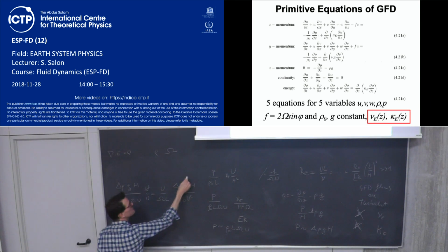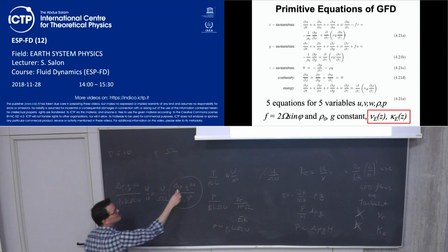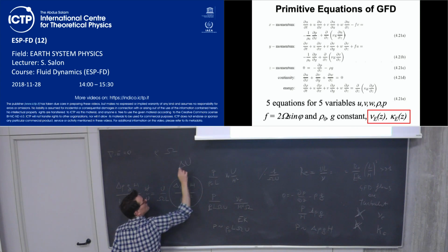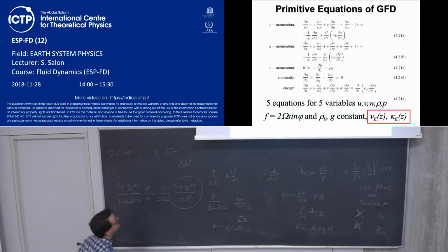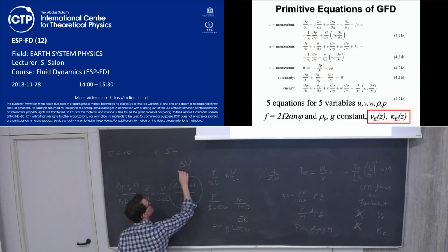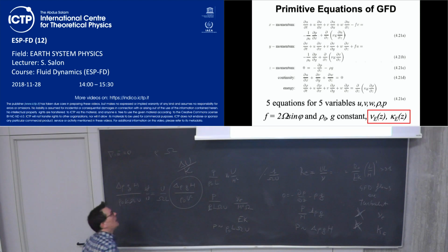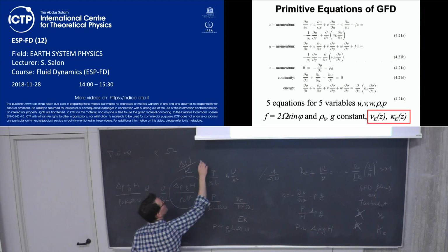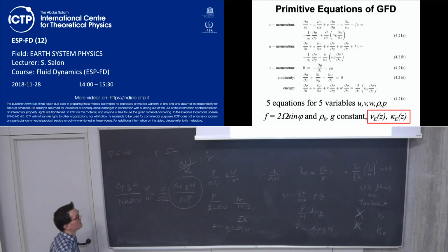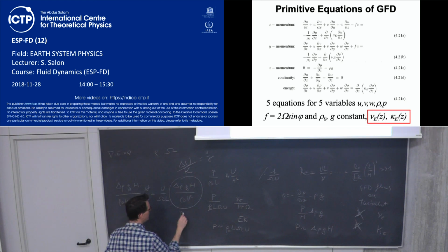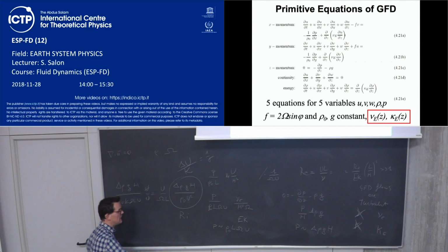Do you remember? This is exactly the scale between the potential energy, U, which is now potential energy. Sometimes it's a little bit funny to use the same symbol, and the kinetic energy. So this is actually 1 over the sigma that we used on Monday. This number is well known again from another scientist, Richardson. So, the Richardson number